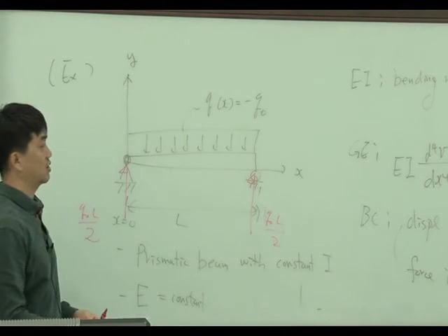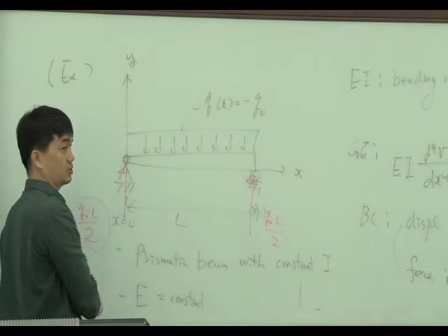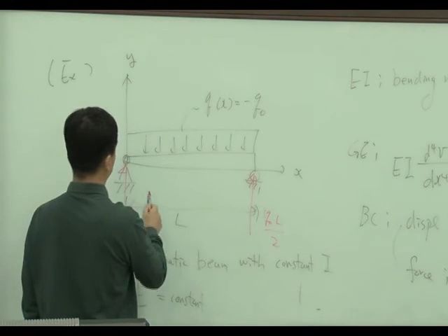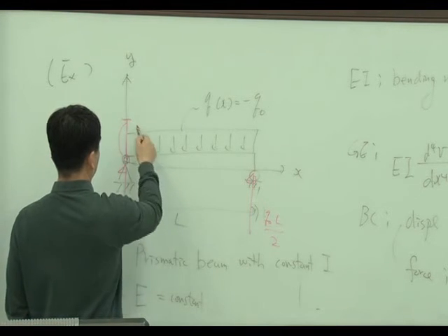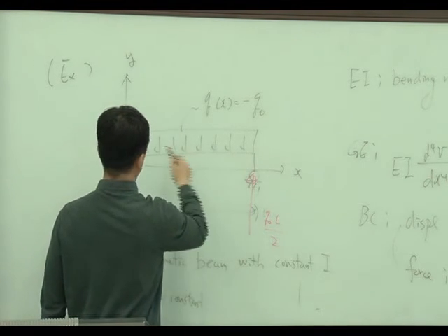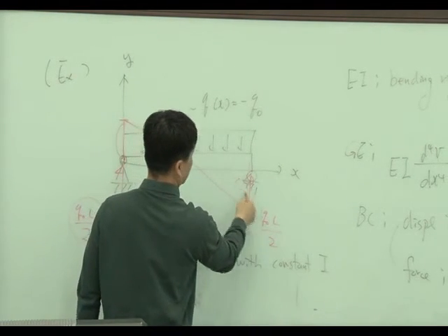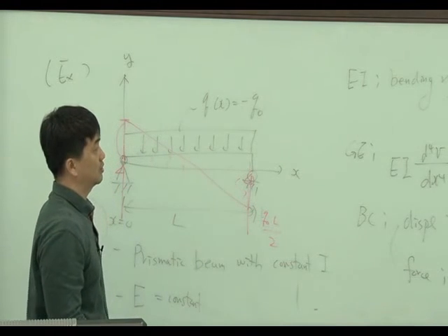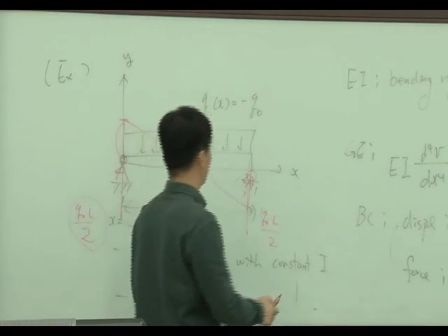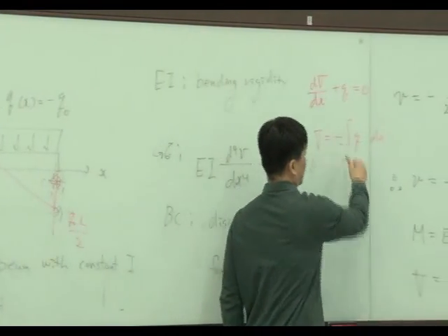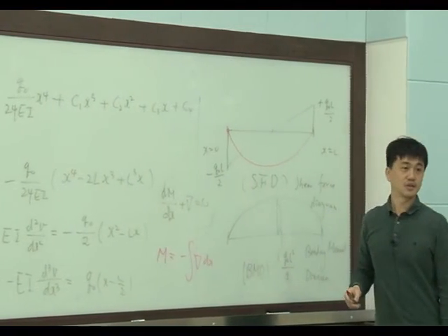From here we can calculate the shear force. If I integrate the load, this point goes up by this value, and this is the shear force diagram. I need to invert it because we have a minus value here. Then we can have this solution.